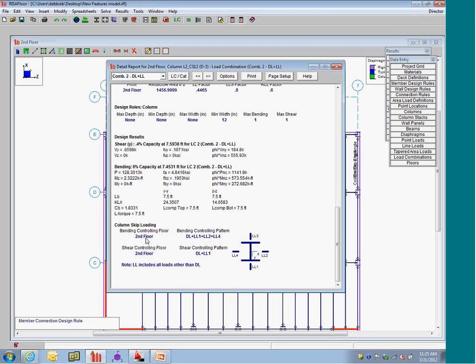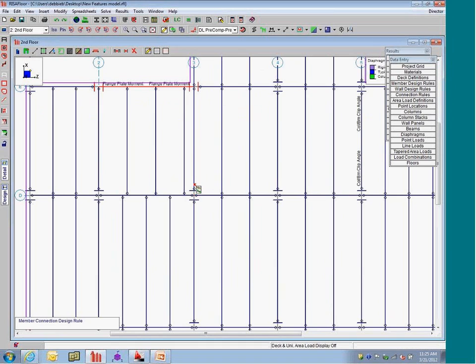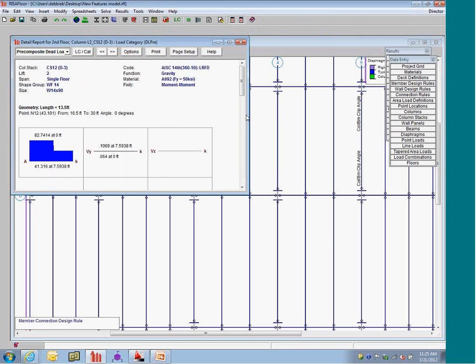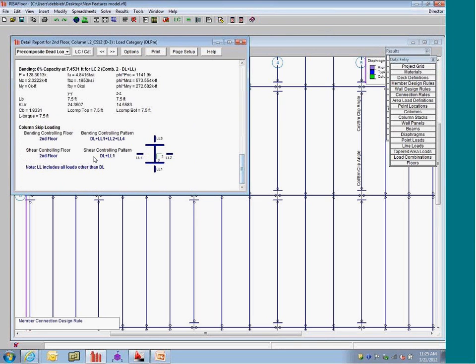So the column in particular, the one that controlled for the bending, shows us that it was L1, this portion here, L2, and L4. So it would be L3 not in place. And we see if we look at that, we zoom in on this column. So without this beam connection, with these 3 load connections tied in there, it would be the worst case for this column. So we actually do a pattern loading, and you can see that it's doing that. It's showing us the controlling pattern.